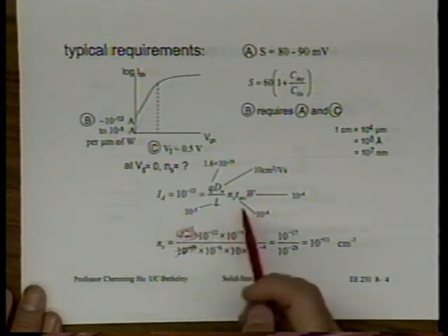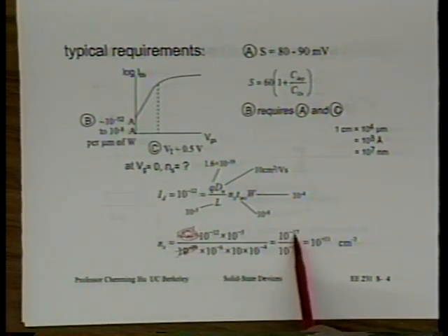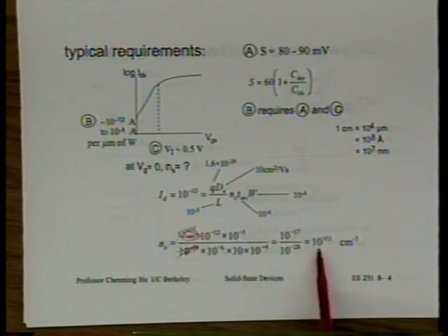I beg your pardon. So divided by 10 to the 19, 10 to the minus 6, and so forth. So we get 10 to the minus 17, 10 to the minus 28, 10 to the 11th. Okay, so they conclude, for low power devices, this is right at inversion, I guess, right? So you just get a little bit of electrons here. By the way, this is an extremely small density of electrons, surprisingly small, perhaps. To appreciate how small it is...